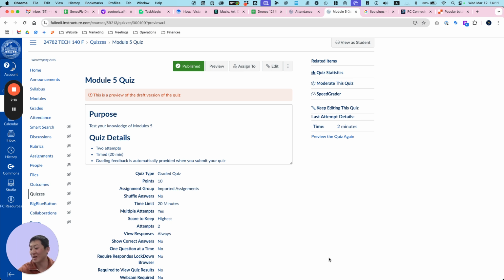So lithium-ion batteries are actually pretty high energy density, which is good when you are putting it in something that flies, because every weight counts on a flying machine. So that's why we use lithium-ion batteries instead of things like lead-acid batteries, because the energy density is much higher. Density, if you might know from physics or chemistry, that's the amount of weight per volume. So when you have the same volume but less weight, that would be less dense.